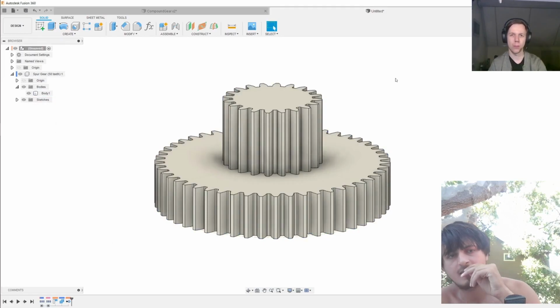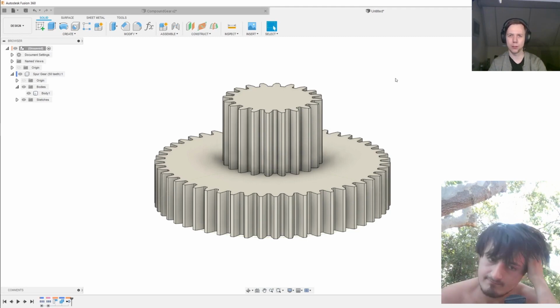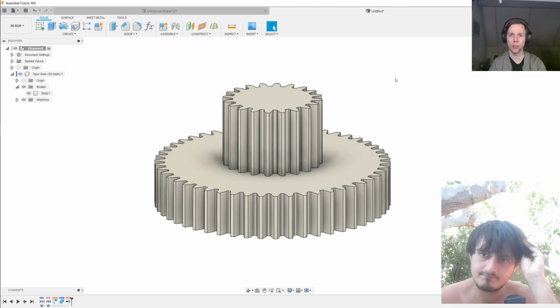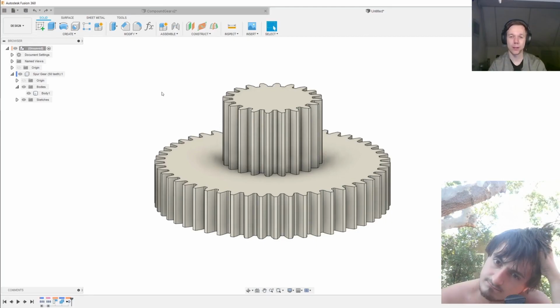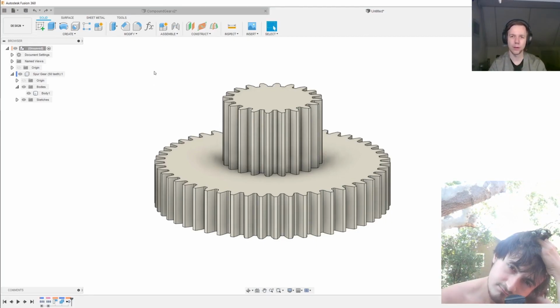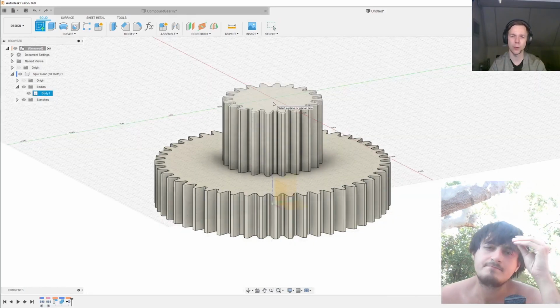There is one unique aspect of compound gears that I would like to discuss. Most gears need to be fixed rigidly to their shafts because they need to be able to transmit torque into or out of that shaft. Compound gears do not need to do this, and so these must be mounted in a way that they can rotate freely with minimal wear and friction. This is most commonly done by mounting the gear to a shaft and then having that shaft rotate between two bearings. But I'd like to show you a different technique, and in this case the shaft is held stationary and the gear will rotate around the shaft supported by two bearings that are mounted inside of the gear.